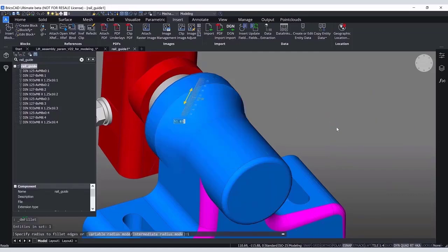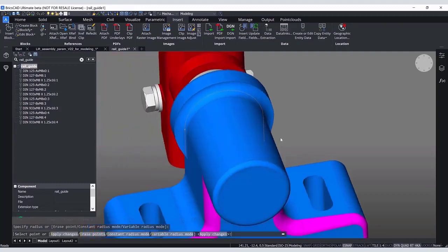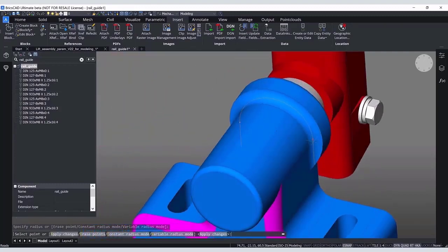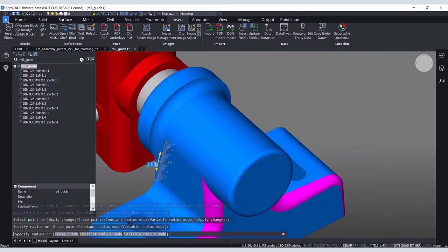Here we want to have 0 radius for ends and some constant radius for the middle arc. How can we do this? If we set 0 radii for both sides, all radii become 0. So we need to firstly set intermediate radii for arc ends and only then set 0 radii for chain ends, like that.